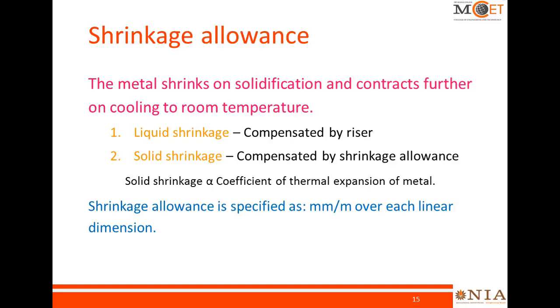So during the initial phase of solidification, the metal shrinks in the liquid stage itself, and that can be compensated by providing a riser. The riser will supply material during the initial liquid solidification. But during solid solidification, once it is solidified, it has become solid.